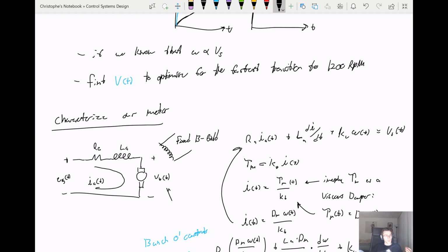So we are supplying voltage as a function of time, current as a function of time is changing, the impedance due to the resistor and the inductance of the inductor within the motor are staying constant, and the fixed magnetic field is ostensibly what the permanent magnets are within a stator of the motor itself. So if we do just a really simple current loop over here, we end up with this equation right here.